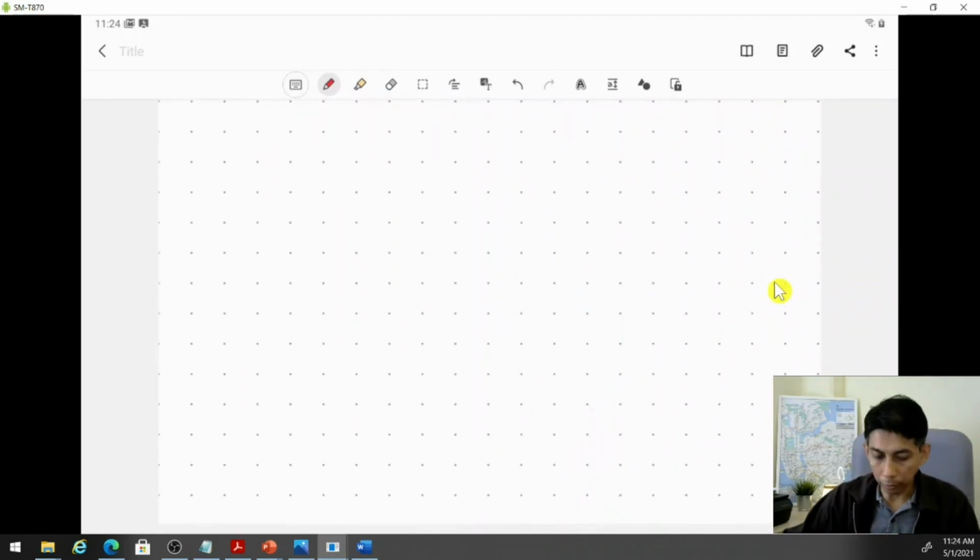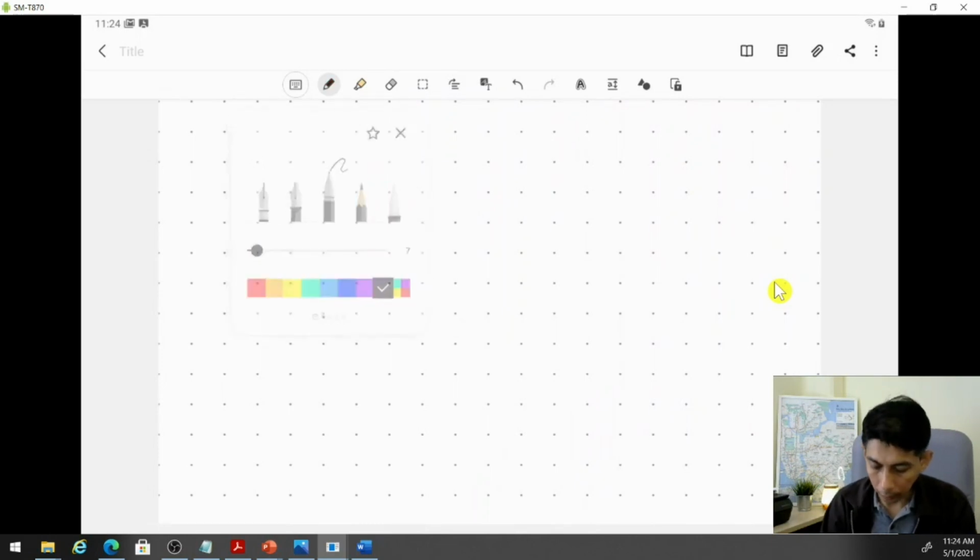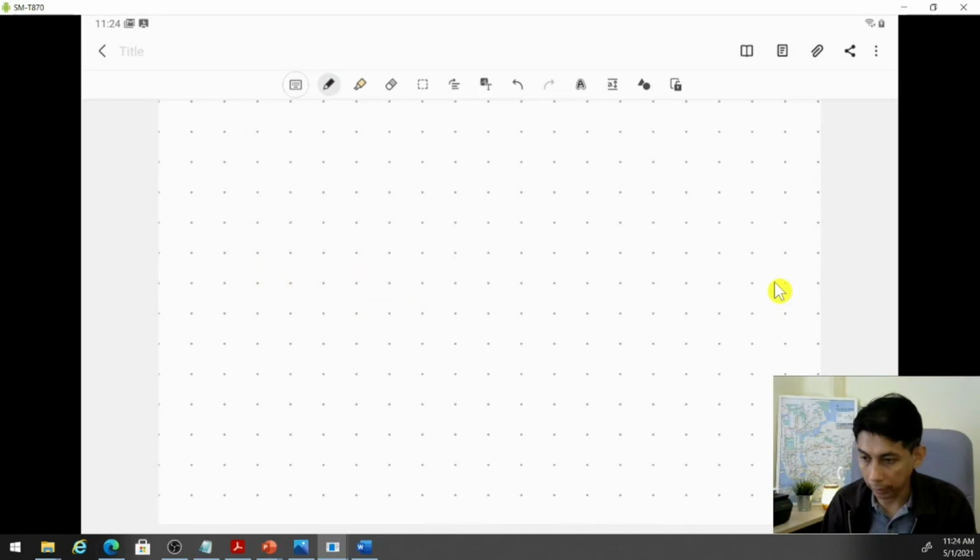To create the CU, we can have the block diagram of the DU and CU already. And remember, the CU is actually a finite state machine, and we will use a Moore type finite state machine.